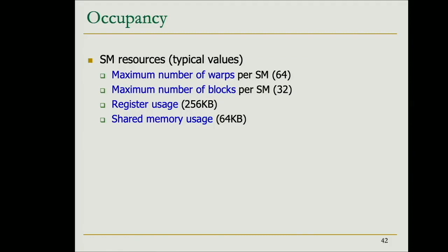Also observe that this occupancy, which essentially you had the definition in the previous slide, is like the percentage of active threads, active warps that we have. This occupancy for the same program might also change depending on what's the actual platform. Why is that? Because if you compare different generations of GPUs, you will see that these numbers have changed a little bit over time, typically increasing, right? That's for sure.